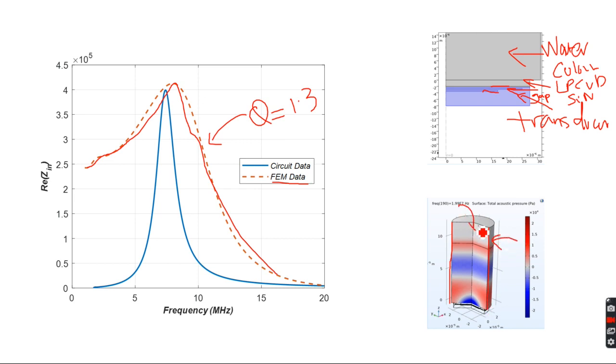First off, you can figure out that this is a perfectly matched layer, a PML, so that you have plane wave radiation conditions and there are no reflections over here. The problem is this also needs to be defined over here as a perfectly matched layer, but it has gone into the model as a sound hard boundary. If you have a sound hard boundary, well, you have a problem, and this is the problem.